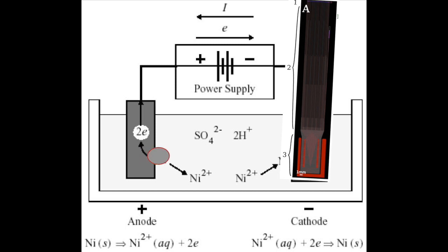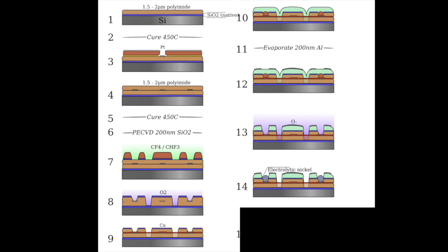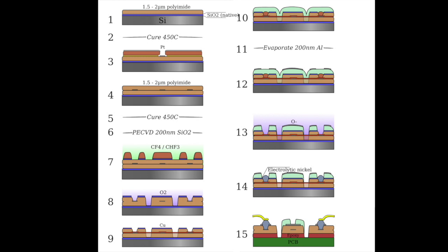Then a current is run through the copper and electrolyte solution, which drives the nickel ions toward the copper buses. This causes a small lump of nickel to form on the end of each thread. This whole stack of materials, which is now the finished thread, is then released from the silicon wafer and laid upon the PCB. The nickel lump serves as a wire bond, where the current conducted through the platinum thread will be transferred to a gold wire that runs to the PCB.